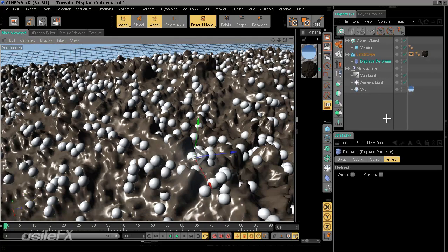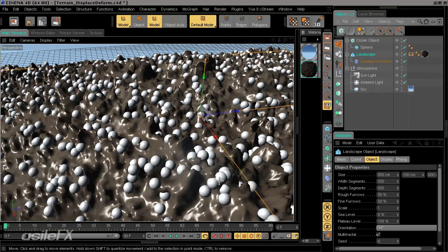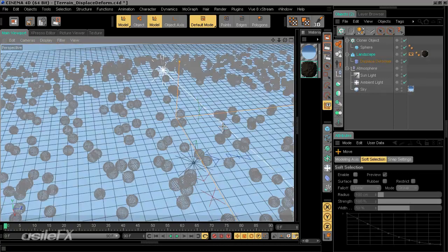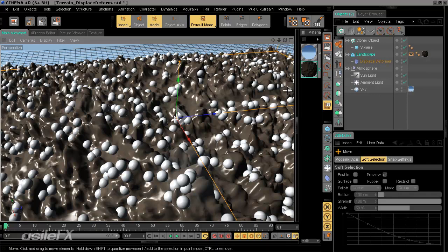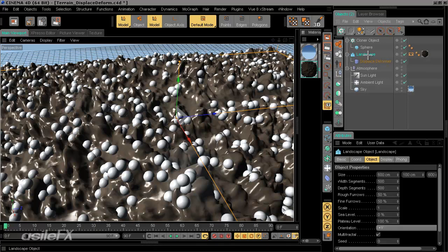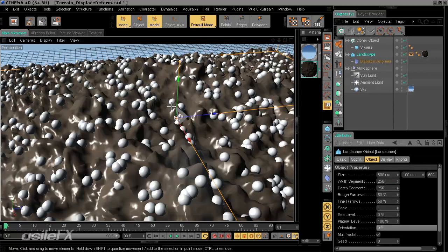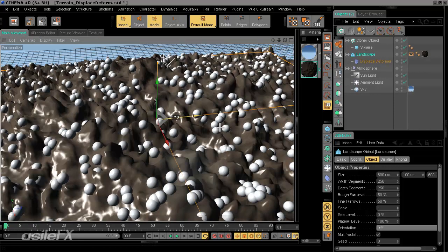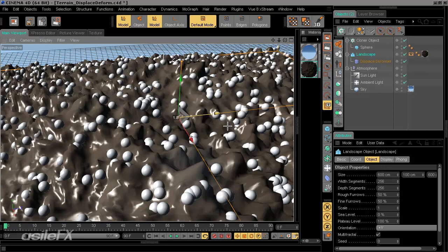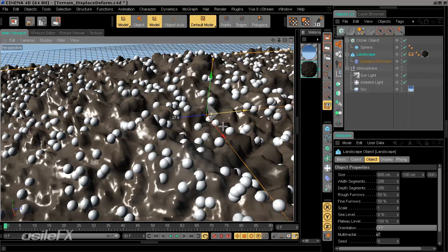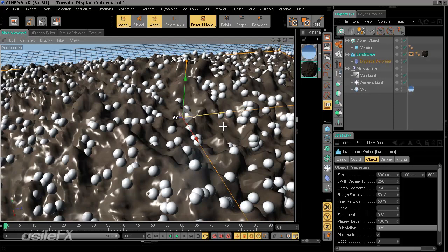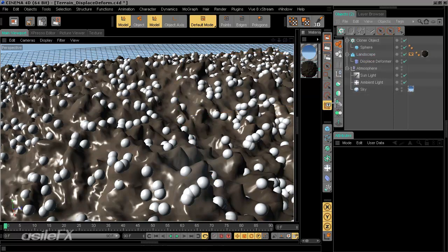Now, if you're using a world mode for the terrain, it should still update, depending on, of course, the size of the terrain. In this case, I did change it up to 500. So if we go ahead and lower it to 56, and now move the terrain, even though the refresh mode is turned off, we can still see the changes through the noise.